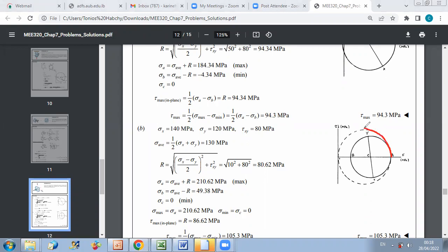It is in the plane corresponding to axis Z and axis A, okay? And you can obtain the maximum shear then by rotating around axis B. So in this case, the maximum shear stress is out of plane and is equal in magnitude to the radius of this circle. And the radius of this circle is simply sigma maximum over 2, so sigma A over 2.